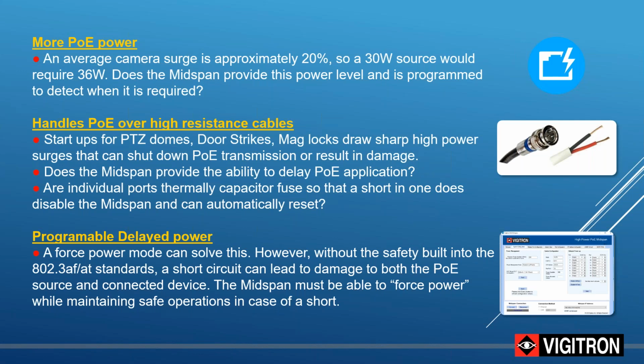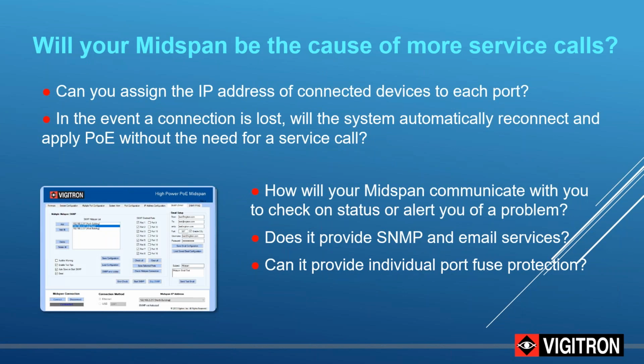Another feature is the ability of programming delays in the system. So if we have high surge startups such as PTZs that, when they're powered up, go to a 0 point position, we can prevent damage to the power supply through high surges. The whole idea is to prevent service calls.